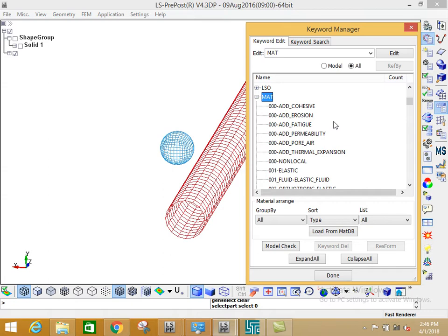So if you want to do that, what do we need? We need this one, the slope. The slope is the Young modulus E. And we need to know this one, this is sigma here. And if you want to model the rest of the curve, we have to select more and more complicated material models. So for the time being, we can just stick with the elastic material model 001.